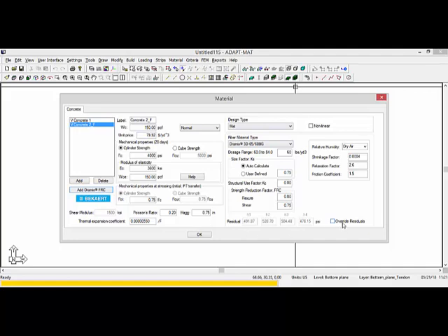designated for the material. The first thing we want to do is set up the design type for the material. So this is going to be a slab on ground, and this is important because it allows the program to filter the type of Dramix fiber that can be used for that design type, whether it be a strain softening fiber or a strain hardening fiber or both. So we'll go ahead and select the option for slab on ground. By doing that, the program will sort the types of fibers that apply to this particular design type.